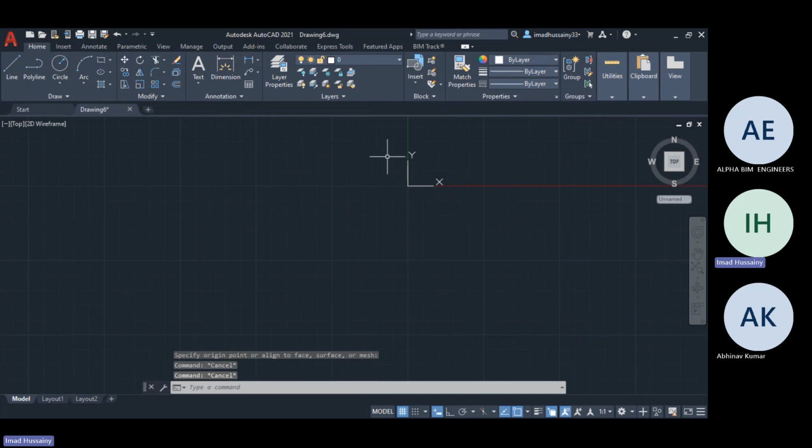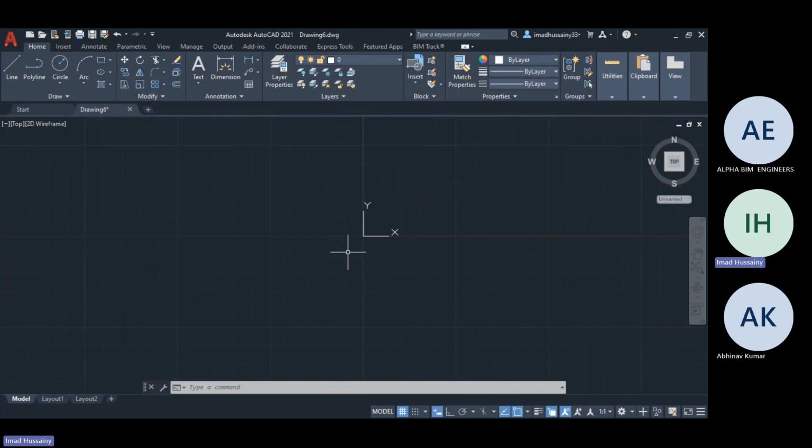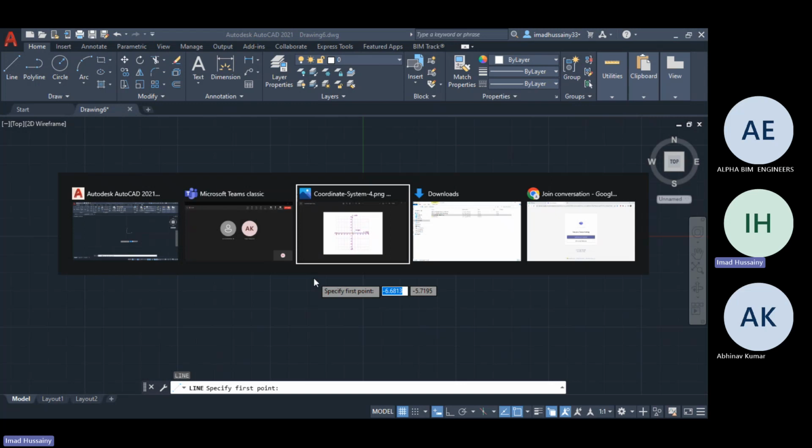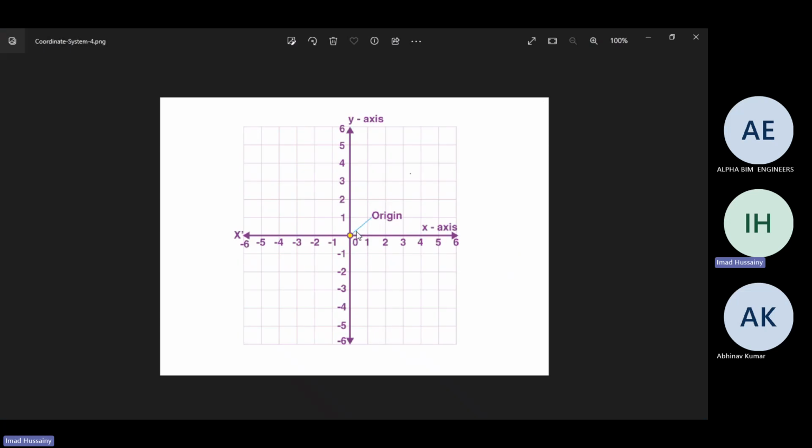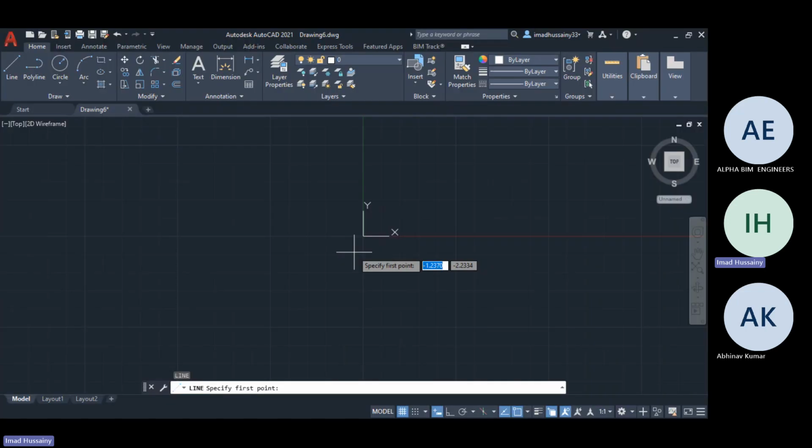Now what is under your visibility? This symbol is for UCS, the user coordinate system. The WCS square box is not showing at all, but it is there; imagine it is there. So you have moved somewhere else. Now I type L, enter. What is my coordinate point, the Cartesian coordinate point, to start from? 0, comma 0 is this.